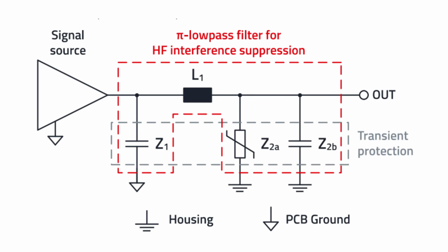Now, Z sub 1 or Z1 is a capacitor, and it can be optionally used to attenuate interference frequencies in the RF range above 500 megahertz originating from the driver. Now, based on practical experience that we have, an attenuation that you want is 10 decibels. It should be achieved at 500 megahertz, resulting in a voltage ratio of V out divided by V in of approximately 0.316. The capacitor impedance Z1, which is capacitive reactance, can be determined using the voltage divider seen here.